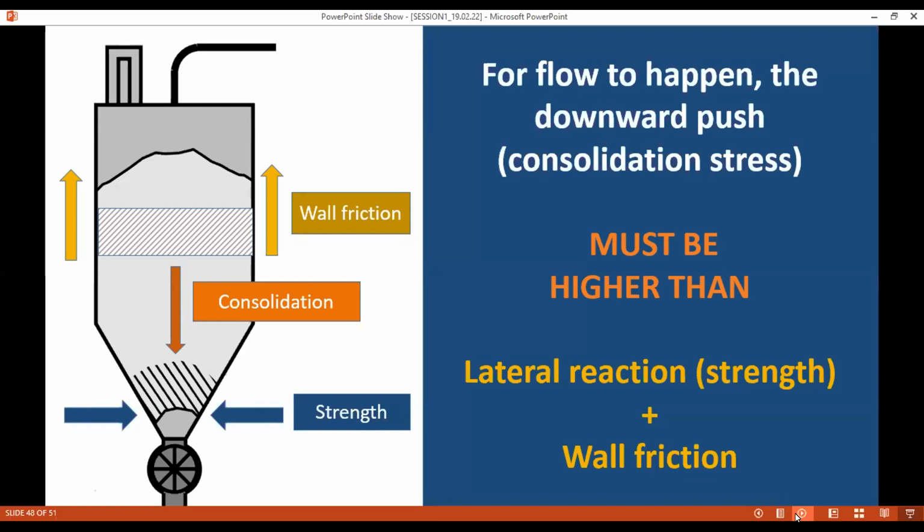The other thing you can do is reduce the friction of the ash with the wall. How can you do it? You can provide more fluidization air. You can have some fluidization pads, and give a sufficient amount of hot air so that you don't inject moisture. We have done it with so many ash samples, and this is brilliant. Invariably, you give a little bit of fluidization air in the hopper, similar to the blow tank, and you start to get a very good amount of ash flow.